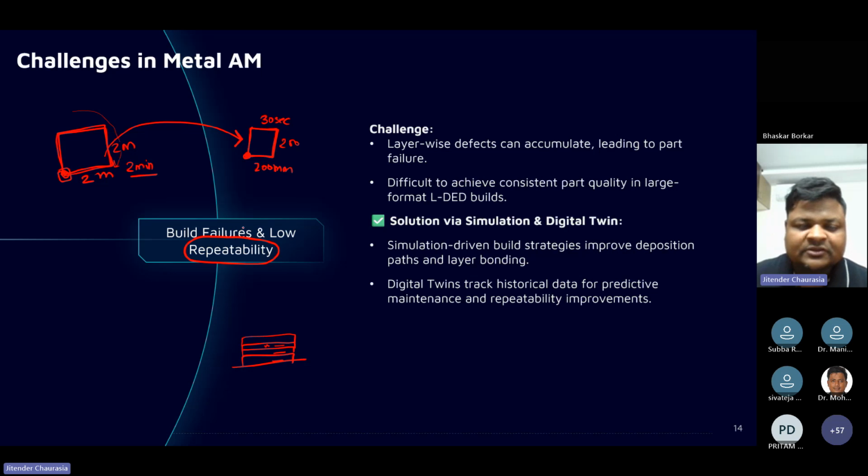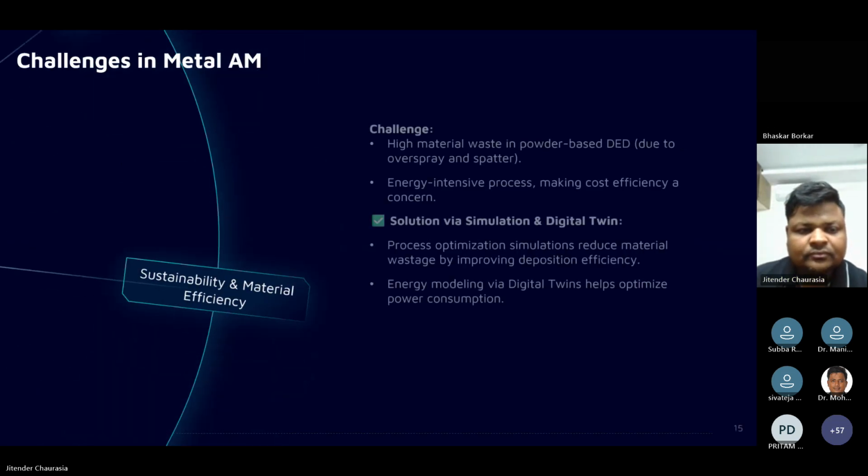I cannot have the same process parameter every time. So in this case what happens is, I need to give an interlayer delay. After finishing one layer, I will ask the laser to wait for some time, then do another layer. So that's how it goes.